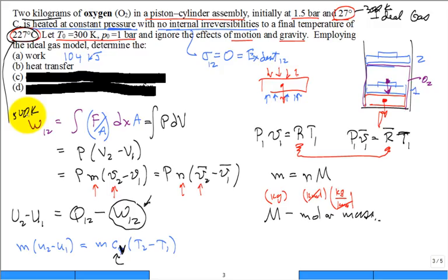So during the process, what would be the good average temperature for the oxygen? Starts at 300, ends at 500? 400. You're an engineer. We make approximations. All right. Don't need to explain that one to most people. They got that one down. Somebody says, I want to calculate this using the tables. I really want to use the table. Table A22, ideal gas properties, and oxygen's in there.